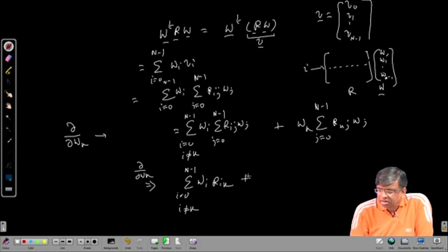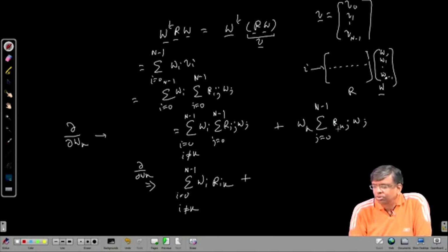And now, here I have got Wk here also, and inside the summation j goes from 0 to n minus 1. So, j will become k once, so that time I have Wk or R kk. So, Wk and this. It is a product of two, this one and this one. You know the differentiation rule: I will first differentiate with respect to this without changing this, and then differentiate this without changing this. Okay. So, if I differentiate this with respect to Wk, I get this term.